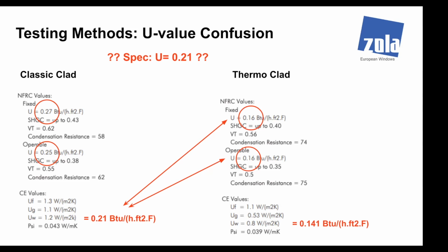Well, Passive House is, of course, component-based, and the CE values allow us to give you the component-based math to do that. We've done in some cases different SHGC for different facades so that you can actually program it. Actually, there was a case where we needed to increase the U value of some of our glass doors to meet the Passive House threshold. There was a request for Krypton, but we do not currently have Krypton available, so we can't boost our doors that way. Heads up, doors do perform less, but we can provide you a door-to-door kind of criteria.